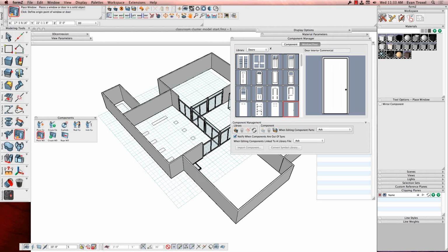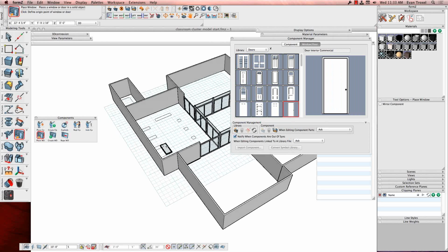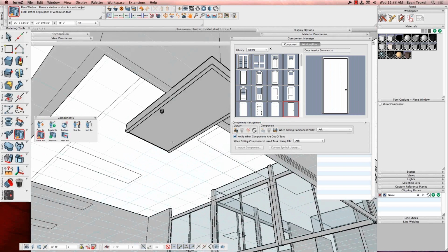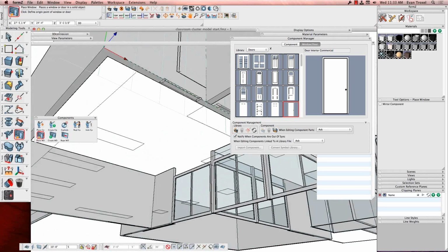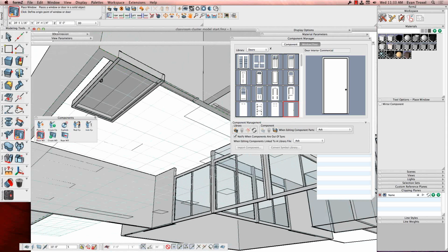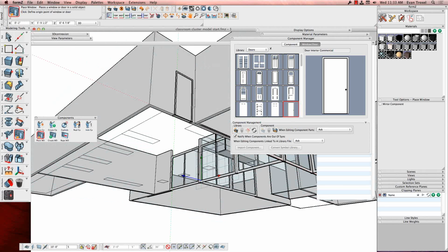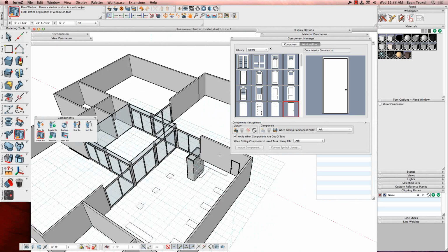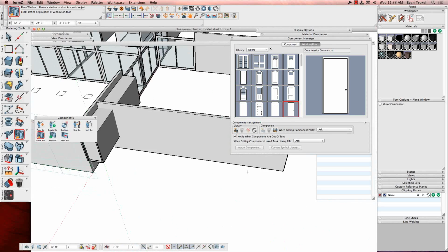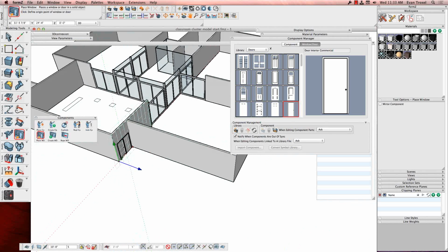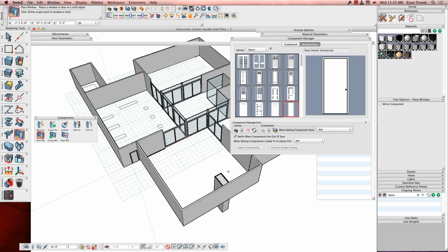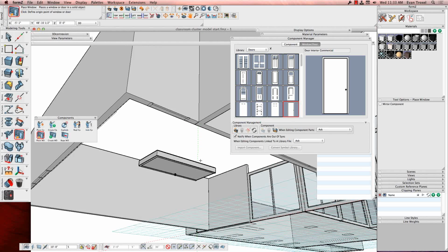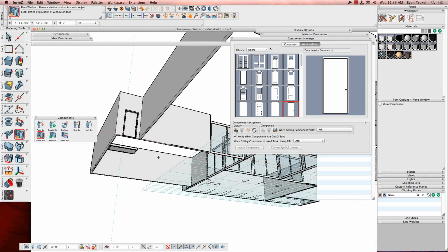And the nice thing about placing doors from the component library, again, I'm just going to zoom in here to where I placed my doors earlier. And let's turn off this lock. There we go. Is that they automatically cut holes in the walls. Okay, so you can see there that doorknob, it's automatically placing that stuff. And sometimes, depending on the view that I'm in, you can see this extra bounding box that shoots back off the door. That's like a void object. That's what it's going to use to cut the hole. All right, so that's kind of a time saver as well.